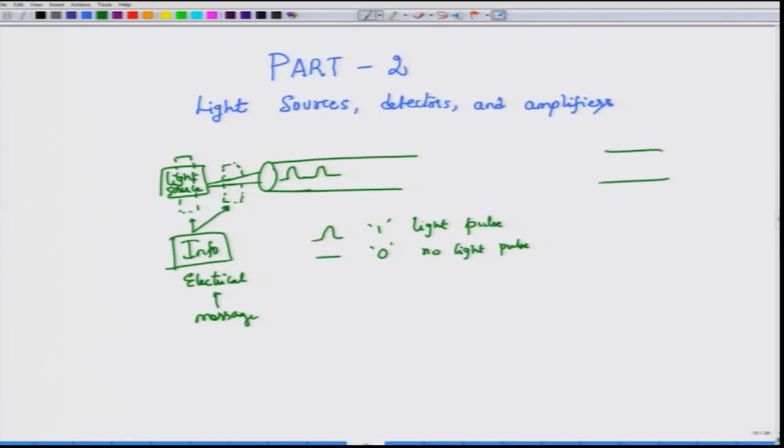So, if the fiber length is very large, say for example 300 kilometers, and you are using a moderate amount of light power, let us say about 1 milliwatt of optical power. Now, recall that 1 milliwatt of optical power corresponds to 0 dBm in the dB scale. This is the launch power of the light that we have sent into the optical fiber, and we know that standard optical fiber has a loss of about 0.2 dB per kilometer.